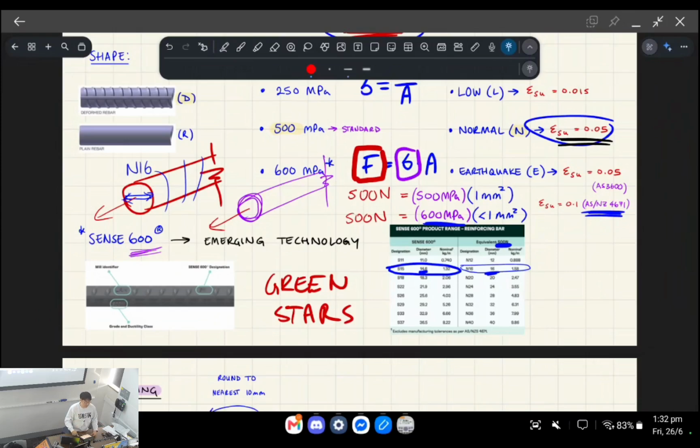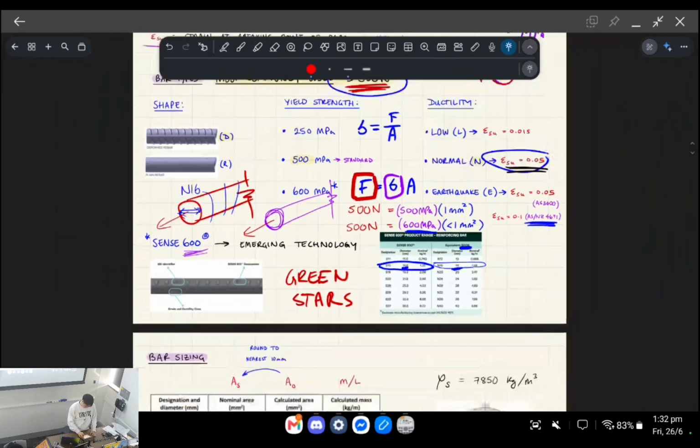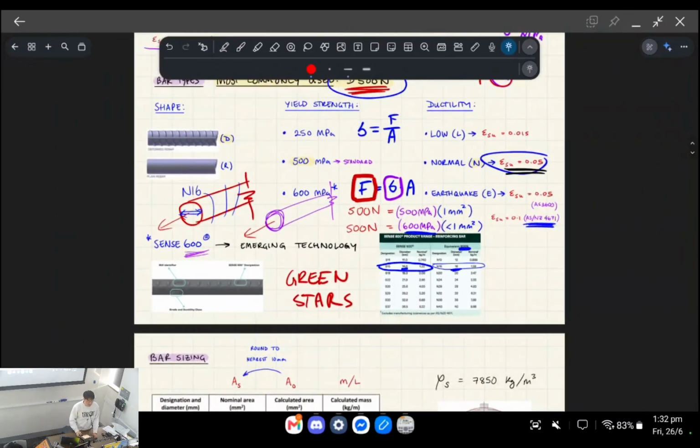But for slabs, you learn about it a little bit in this course in week 9. For slabs, it's actually deflection governed. That structural element is deflection governed. It's not strength governed. So it's not a good idea to use this product. This isn't a magical product that solves every problem. Yeah, it's not a good idea to use this product for slabs. Okay.